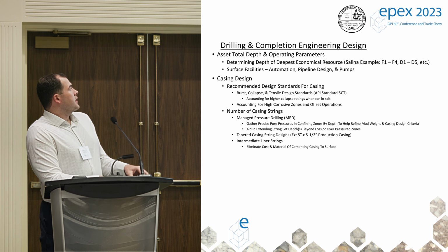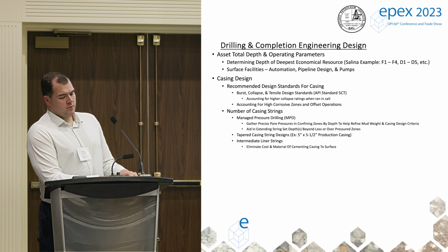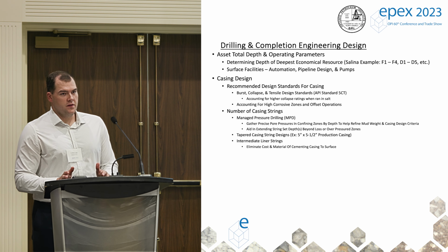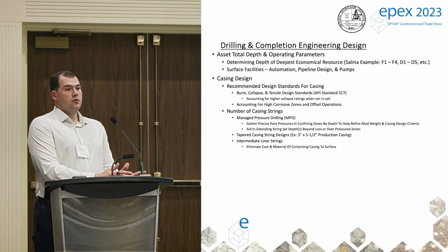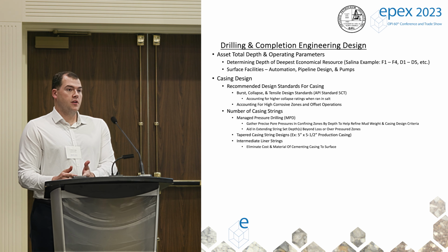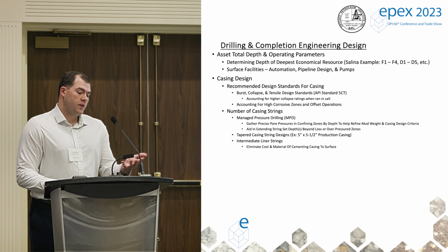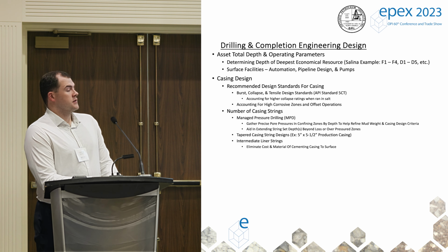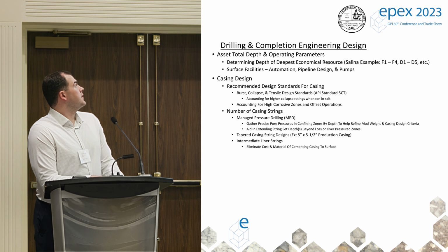Whenever designing your casing design, I've seen some very precarious ways of designing it that have evolved, I would say, on this side of the industry as a whole. I would redirect everyone back to API standards as far as tensile, burst, and collapse ratios. With the upside, if any string is set in salt, I would increase the safety factor as recommended.